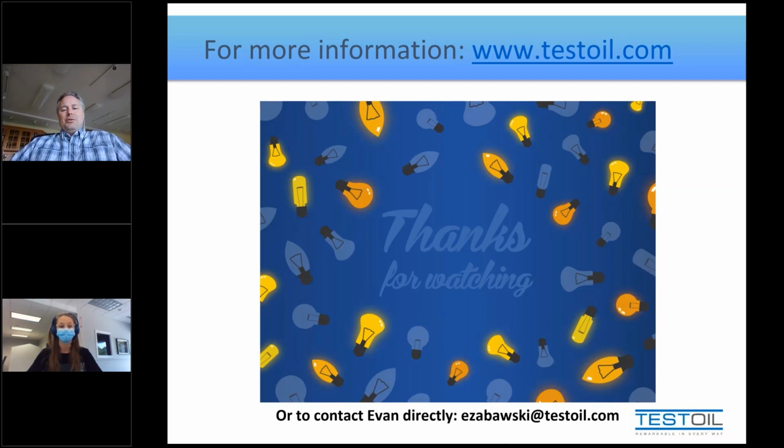Because generally speaking, there's usually more than one choice. Sometimes you can filter, sometimes you can bleed and feed, and in certain cases you can actually re-additize the oils. There's lots of options that exist. But no, a report's never going to come back to you with a definitive, big green check mark beside change your oil, is the only option.